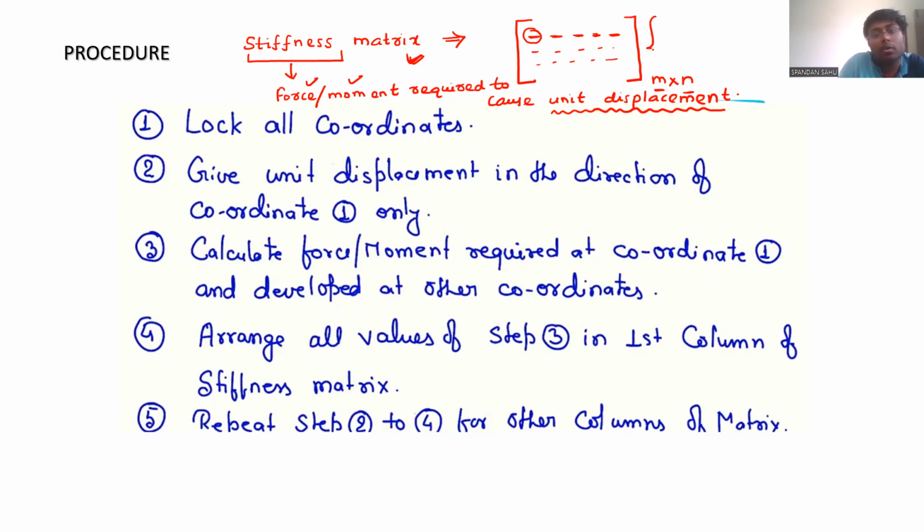And then what will be the unknowns related to it? The unknowns related will be displacements, because you are taking displacements as units, as unity. But at that joint, it need not be unity. The rotation might be some 0.3 radian, 2 radian, who knows? It should not be 1 unit or 1 radian. I am not telling it cannot be 1 radian. It can be 1 radian for some loading condition, but not all the time. So for simplicity, we are assuming our displacement to be unity.